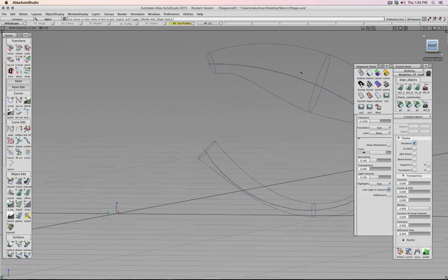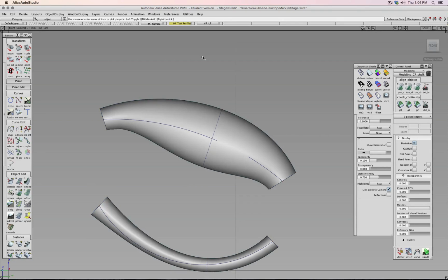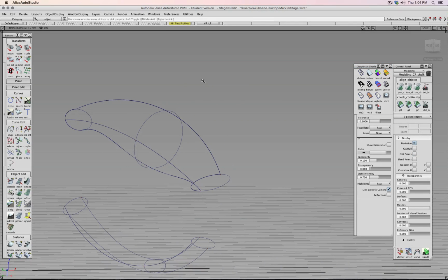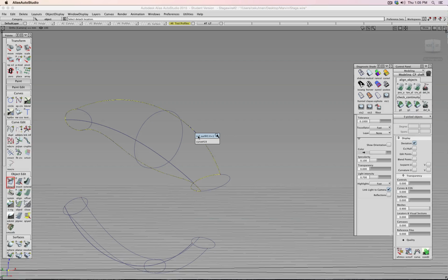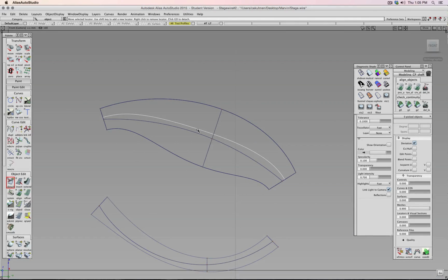And I would like to have a line that flows that way. So one easy way maybe to get an idea is to copy and paste this surface onto this layer, and then that surface I'm going to split with the detach command. So detach this surface along here. Let's go to a side view, maybe press Control.